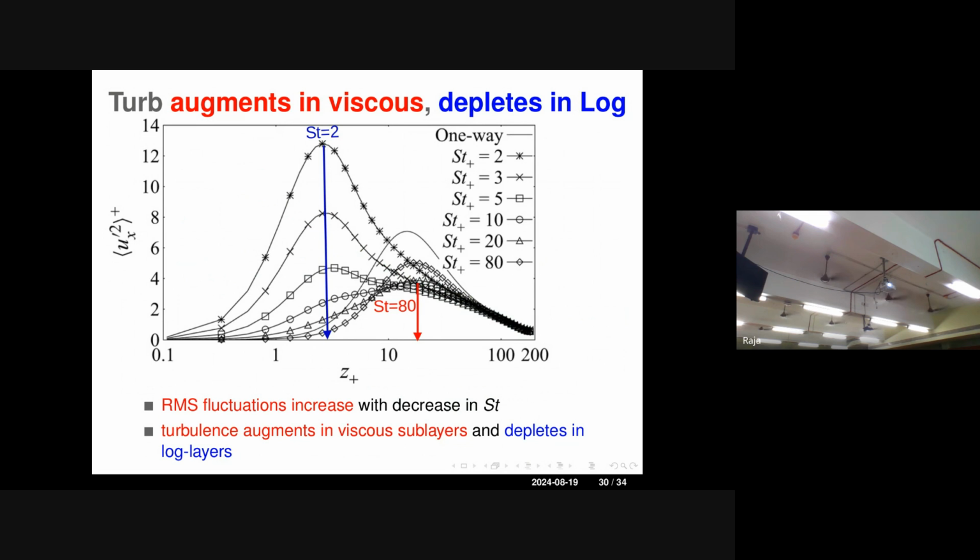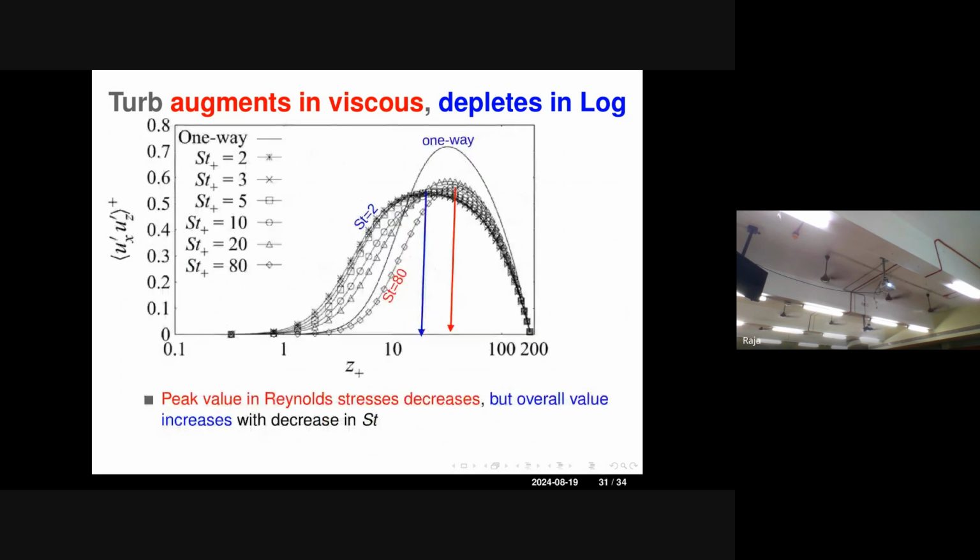Near the logarithmic layers, modulation of the turbulence really happens. So this entire RMS fluctuation gradually changes in the system. What we are seeing as the continuous line is typical wall bounded turbulence, but if we put more particles into the system in a very non-monotonic way, it will be modulated. The Reynolds stresses also change in the system. The Reynolds stresses effectively decrease, but your mean gradients at certain layers increase.